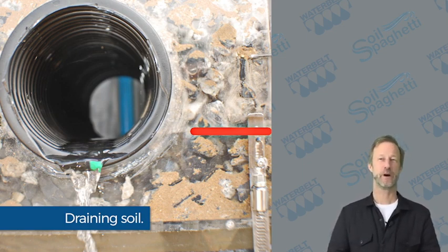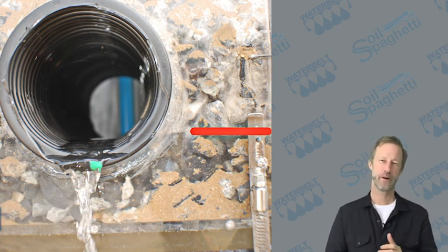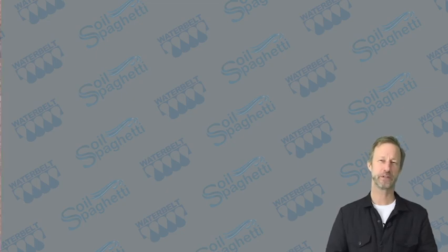Phrased differently, while the source for groundwater is rainfall from above, from a drainage collection point of view, the source is always a rising water table from below. Drainage must always be oriented to intercept the rising water table. Now on to the problem of blocked pipes and filters.